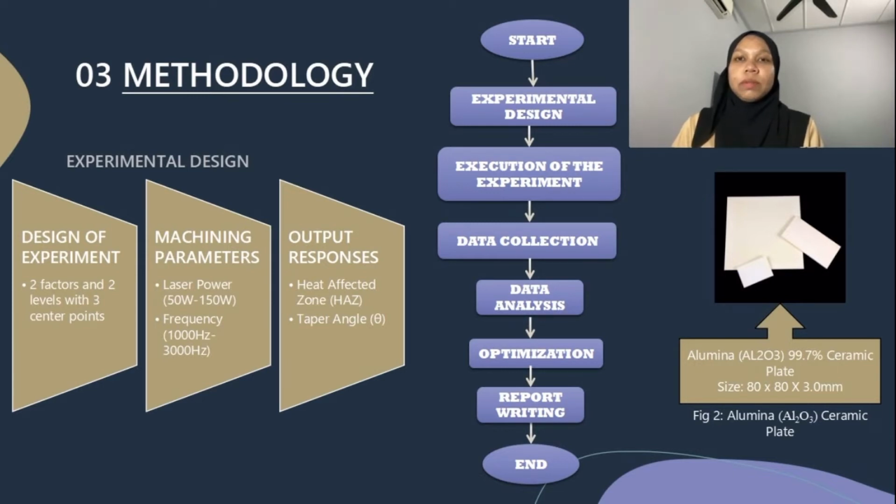The machining parameters evaluated are laser power from 50 watt to 150 watt and frequency from 1000 Hz to 3000 Hz. The output responses for this project are heat affected zone and taper angle. Next, the execution of the experiment. The experiment was executed using the experimental design, and the data will be collected during the experiment using a scanning electron microscope (SEM) machine. The data analysis is done using Design Expert software version 6.0.8.